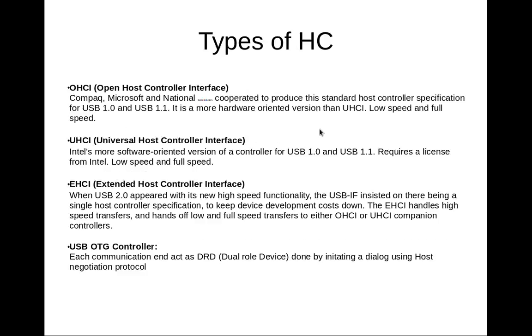There are some standards of host controller. There are many controller interface standards, and I'm going to talk about only 4 as of now. One is OHCI, which was developed by Compaq for USB 1.0 and 1.1. And you have the Universal Host Controller, UHCI. This was Intel's one for USB 1.0 and 1.1, but it required a license from Intel, and it's for low speed and full speed devices.